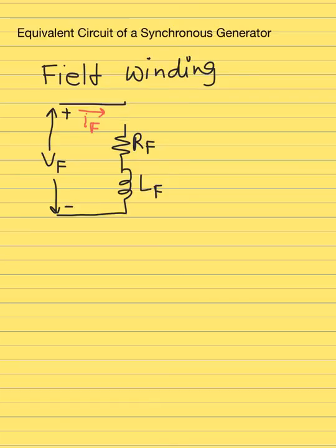Let's say this is the resistance R, adjustable value, and I'm gonna say it's a variable as well. So this arrow shows that this value can be 0 or it can be any non-zero value as well. So it's a variable resistor, and it's an externally added resistor to control the current in the field winding. So that's the field winding.